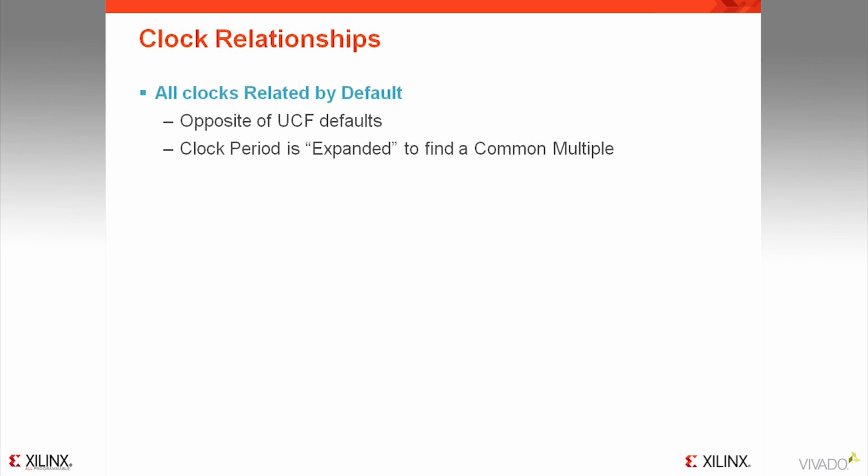In most designs, there are many clocks. A critical difference in Vivado is that all clocks are assumed to be related, meaning if there are paths in the design where data can be captured in a domain that was generated in another, it is reported by default. This was not the case in UCF with ISE. All clock periods are expanded, meaning the waveform is repeated out many cycles, and the tool looks for a common alignment point. If it cannot find one, it uses the smallest window and performs analysis based on that. ISE would not attempt to calculate the timing on these paths unless the user expressly related the clocks. This is a convention adopted by all SDC-based timing tools.